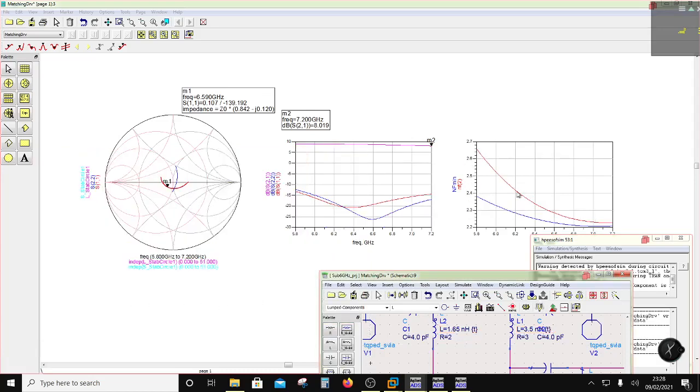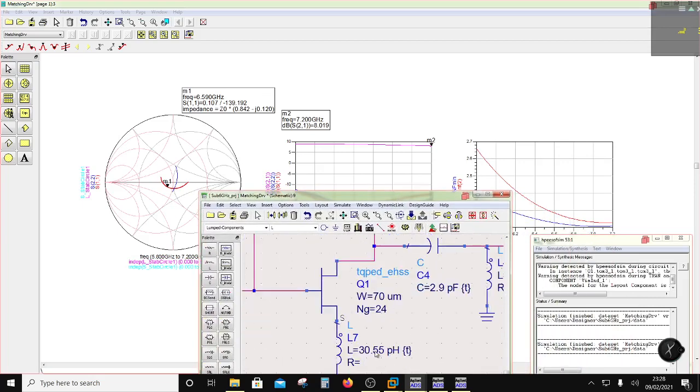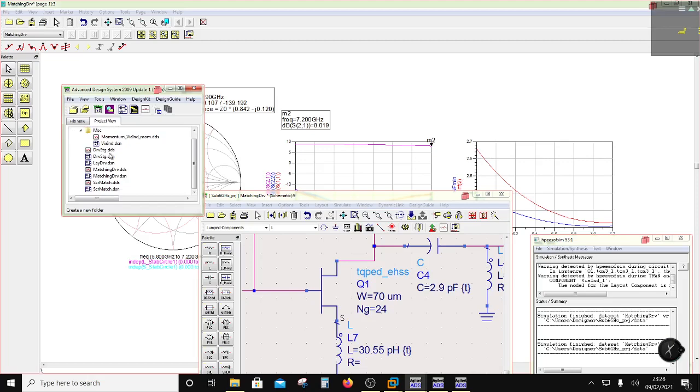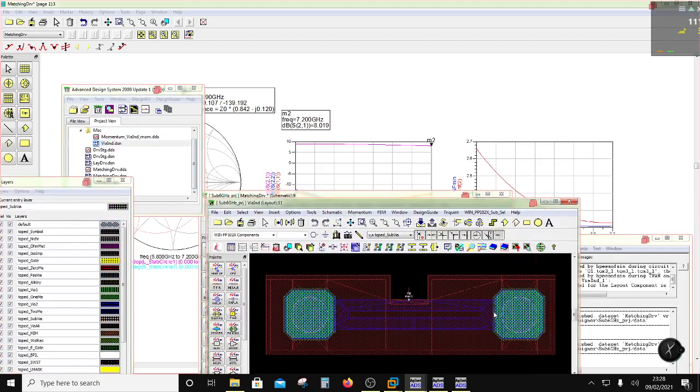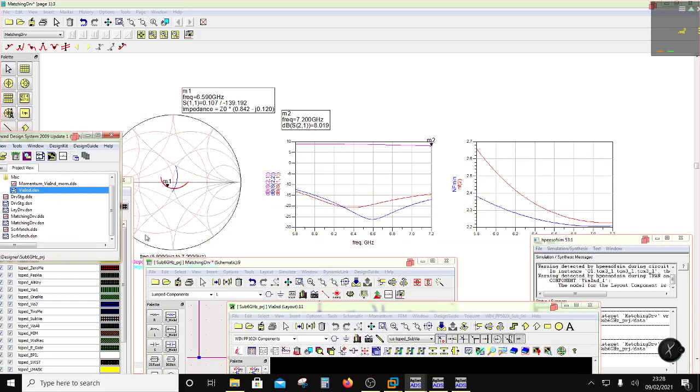So now this noise figure can be improved because it's a function of this, right? Now you would have to go ahead and create this by taking the via. So you take that via and you are going to spread them apart more so that there is more inductance added here and here, right? Or you make this thinner, this trace thinner, so that the source inductance can go up. So that way you can also control the noise figure, right? So I have told you a number of things. It's just not matching, also the stability, the bandwidth, the gain, right? And also the noise figure.